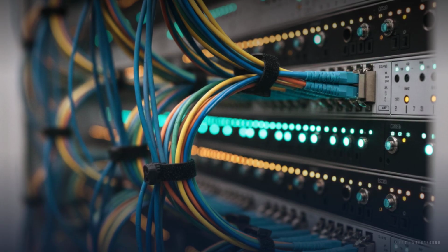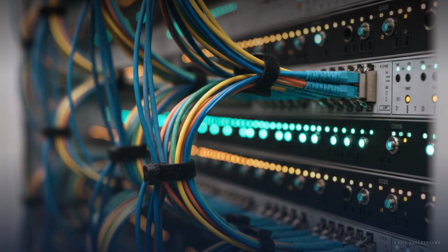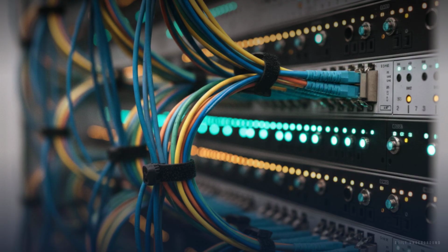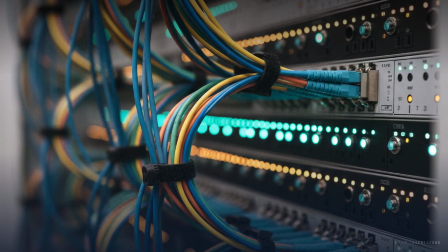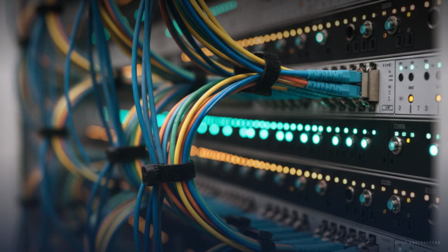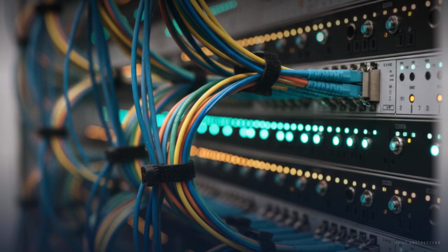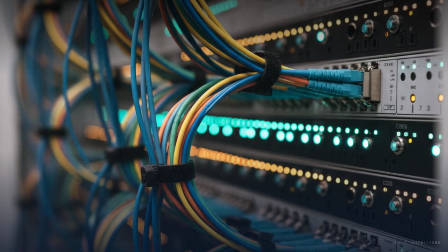If the entire A-side power system fails, every component from the utility feed to the distribution board, the B-side takes over instantly. The servers never lose power, the switch is seamless because both paths are live simultaneously.